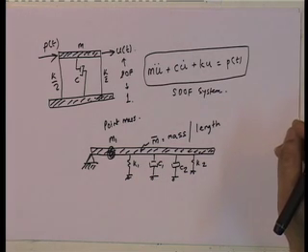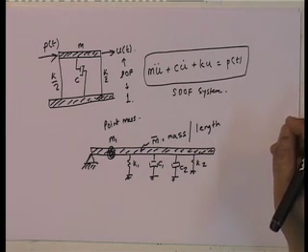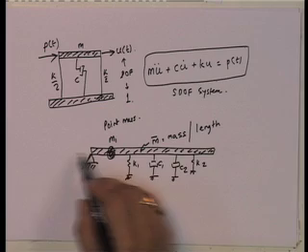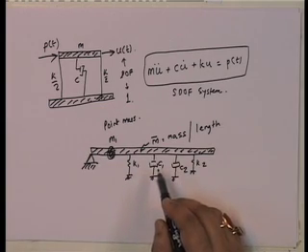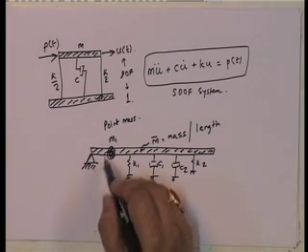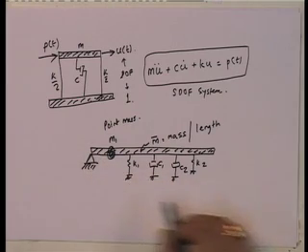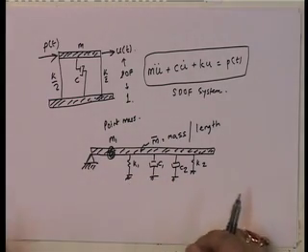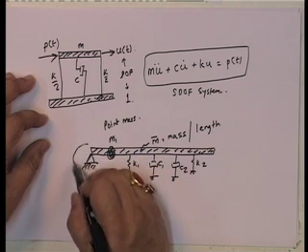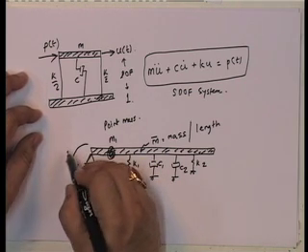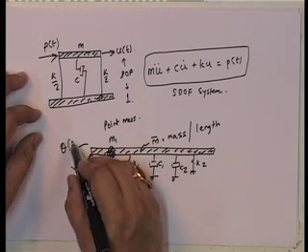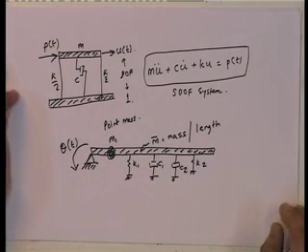So, now let us look at this particular system. If you look at this, is this a single degree of freedom system? Well, this is a rigid bar. So, what can it do? It can rotate about this point. Now, note that one of the fundamental points is that it can rotate. So, I can define theta t as my degree of freedom.